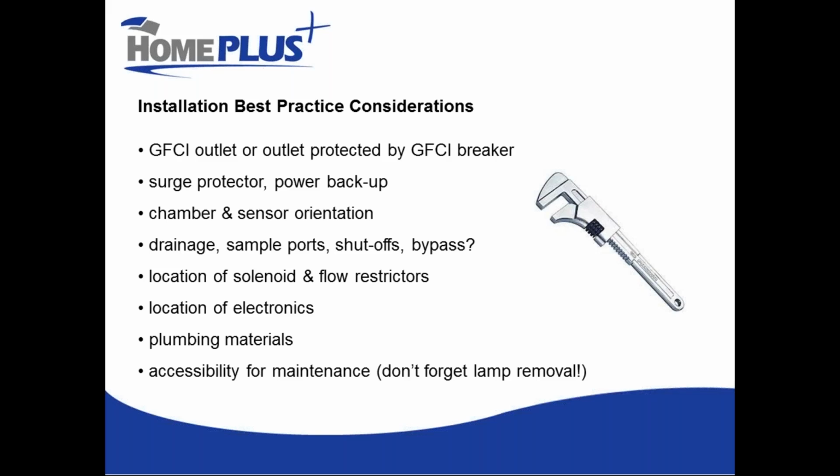Most regulations from the health authorities prohibit a bypass. It is something that can be allowed under certain circumstances if pre-arranged with your drinking water officer, but generally speaking, UV bypasses are not permitted.